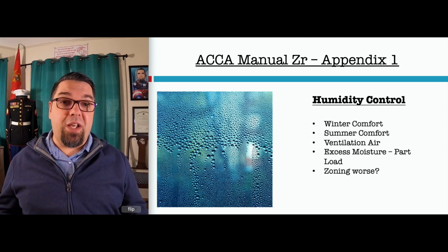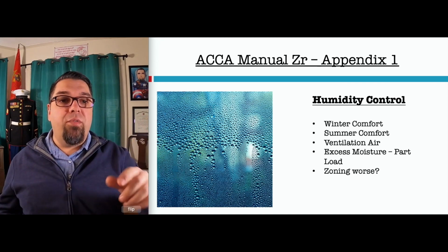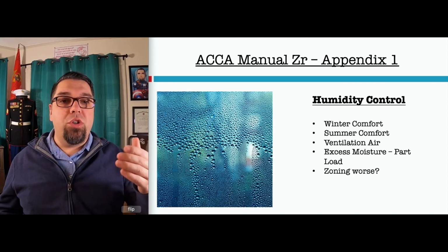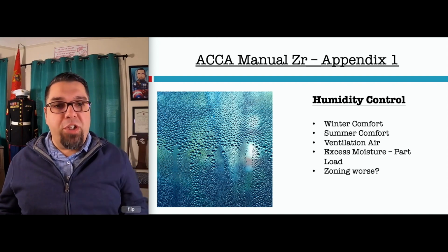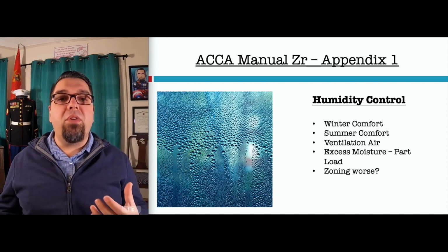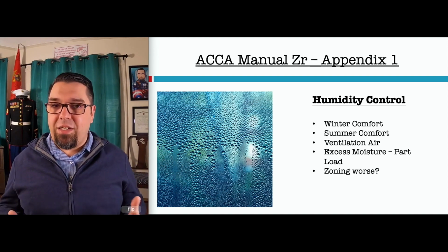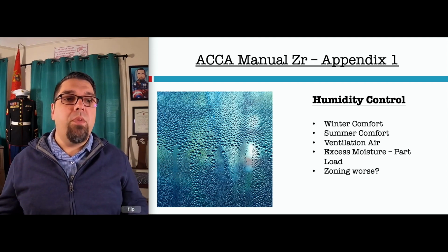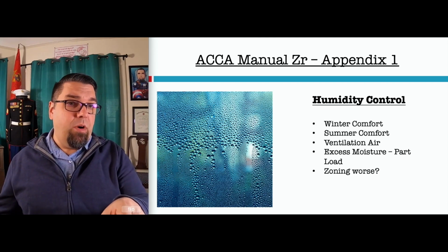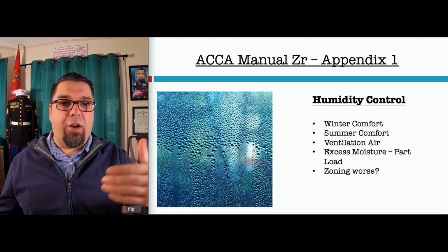And in the summertime, it's just as important, because if the temperature of a wall or window or door gets below the dew point of the air, you're going to get that moisture like you see on this window. Now, we typically see this a lot when we over-humidify in the wintertime. It's really easy to do this. That's how we know we're adding too much humidity. We would turn the humidifier down, right? At this point, it's too late, obviously, because now you're seeing visible moisture. Who knows what happens when you talk about infiltration inside a wall and all that stuff.